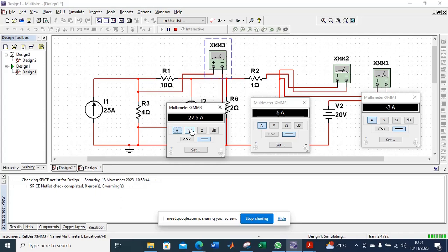So I should just go to this volts. I remove the amps and put volts. If I put volts, you see the simulation is still moving on and the currents readjust themselves. It has gone back to 10 amps this side and 8 amps this side. So if I'm looking for the voltage drop across the 4 ohm resistor, it will be 80 volts.